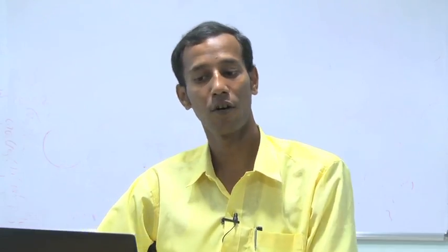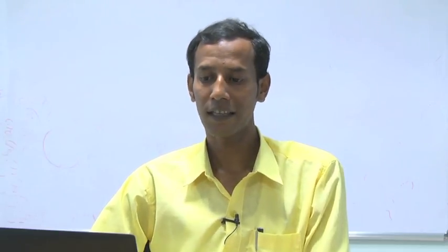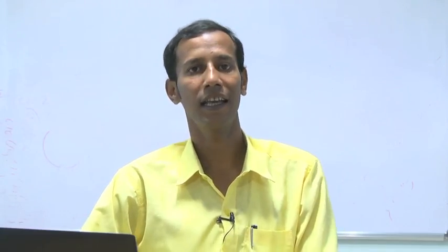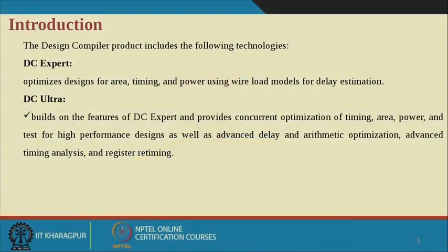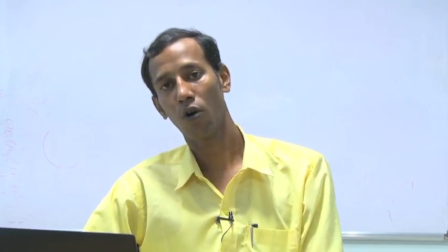Just like DC Expert, it can provide optimization in terms of timing, area, power, everything, and along with that it can do advanced delay and arithmetic optimization, advanced timing analysis, as well as register retiming or pipelining.